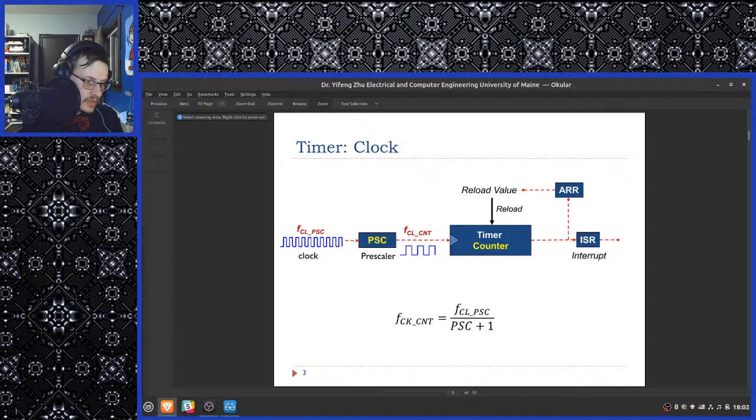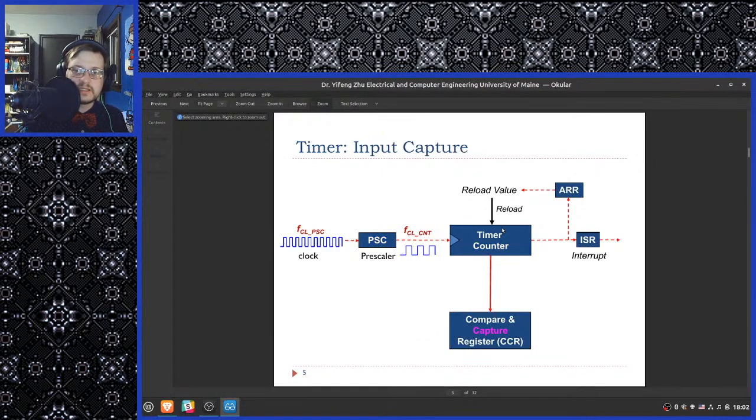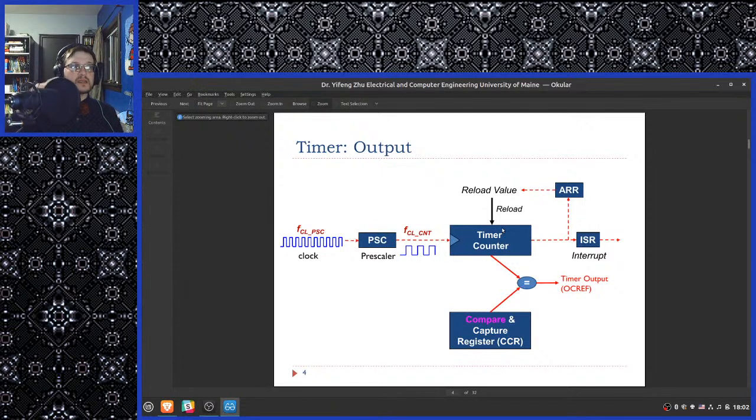So how would we read the captured time by the CCR using code? Well, we're not quite there yet, but you would be reading it in the same way that you would read your GPIO pins. The same mechanism. Since it's memory mapped, you find the address which it has been mapped to, and you dereference the pointer to grab out the data.